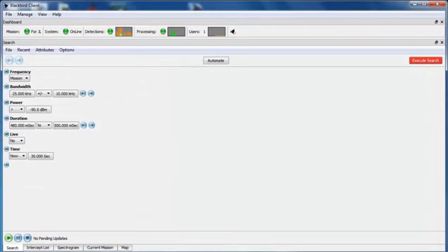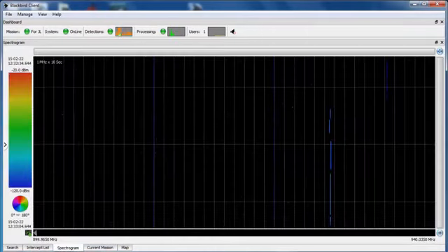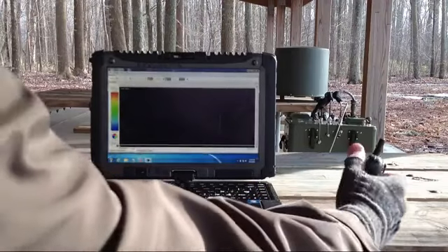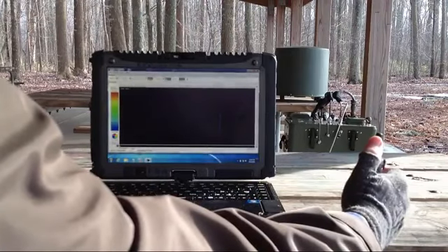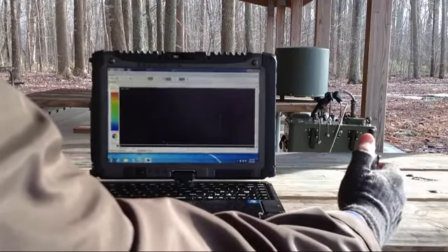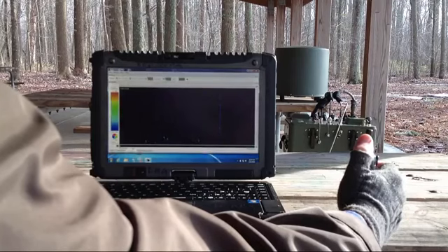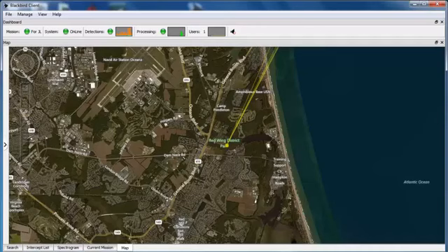I have created one called 4JL. This simple detector describes the signal in terms of signal bandwidth and signal duration. The effect of the detector is to filter from the spectrogram display any signal that does not meet the criteria in the detector, which also removes all the bearings from the map except those that meet the criteria for this